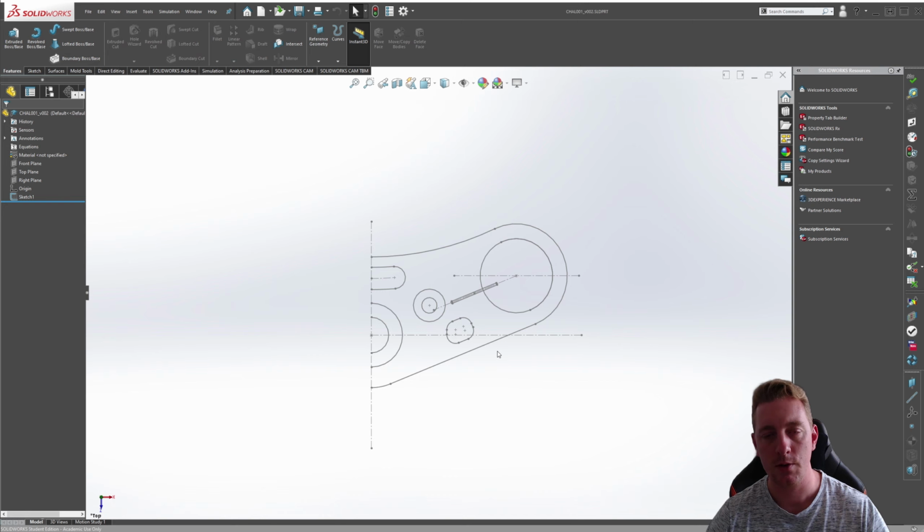With this first sketch done, we can now move on to the next part, which is actually building the two intersecting bodies. The reason why I did the sketch first is when you create an intersecting body from a sketch, you can't add all these finer details in there because they can't be reused after the intersected bodies have been created. So what I like to do, I create this and then I can use the overall shape of it to create the first body.